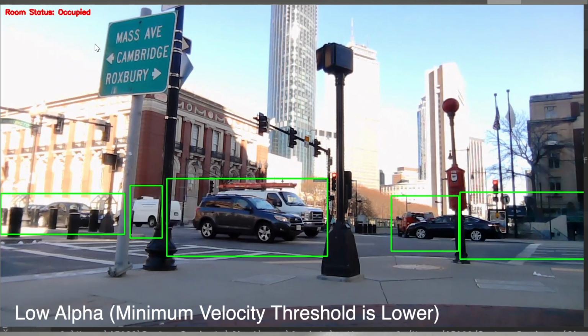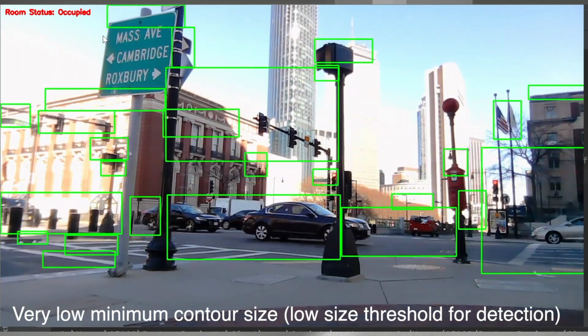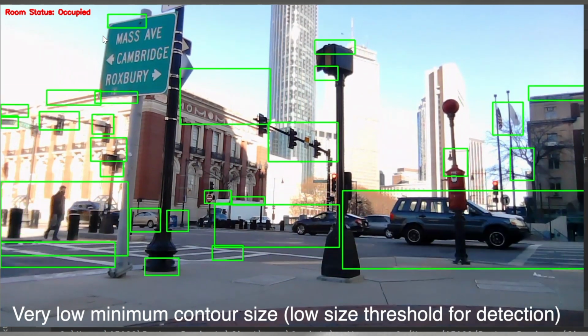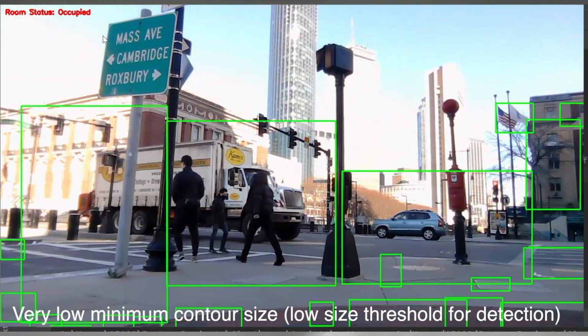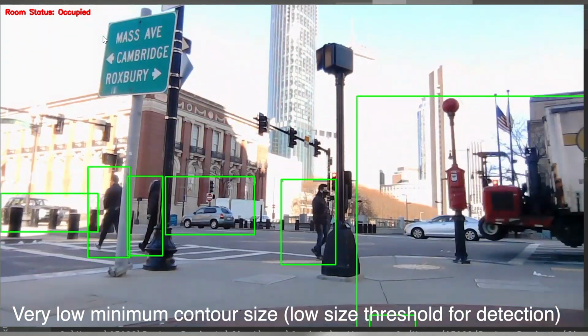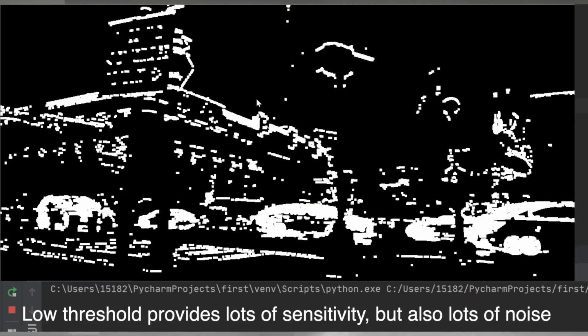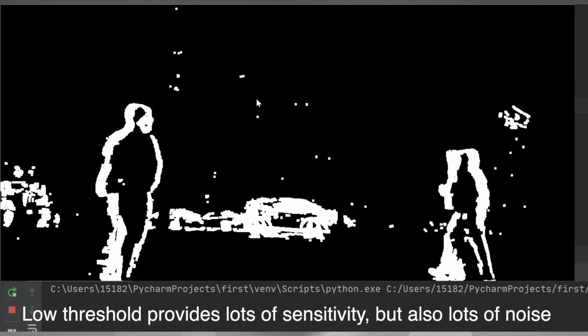The minimum contour size is another adjustment that we can play with, which adjusts the object size our motion detector focuses on. This type of motion detection is also quite versatile. It can detect fast and slow-moving objects quite well. But when it comes to disadvantages of this type of motion detection, well, it's hard to think of many, but obviously a computer is required. Also, adjusting any parameter means that some sort of trade-off is made, which can make it difficult to sometimes find the parameters that are just right.